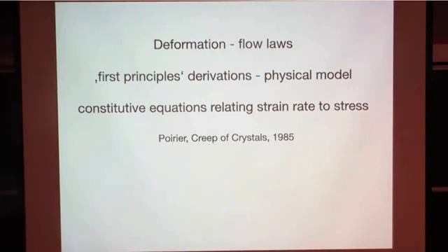So, moving on to deformation and flow laws. By the way, just ask questions if I'm going too fast here. A first principles derivation, a physical model for deformation based on point defects, leads to these constitutive equations that have come up a number of times that relate strain rate to stress. So now we're getting actually a time in there. This is the proper equation for deformation. One example of a book where you can look that up, of course, that goes much further back than this, is Poirier, Creep of Crystals. That's a relatively thin book, quite some time ago, but the basics are still there and are relatively nicely explained. There are a number of other books as well.